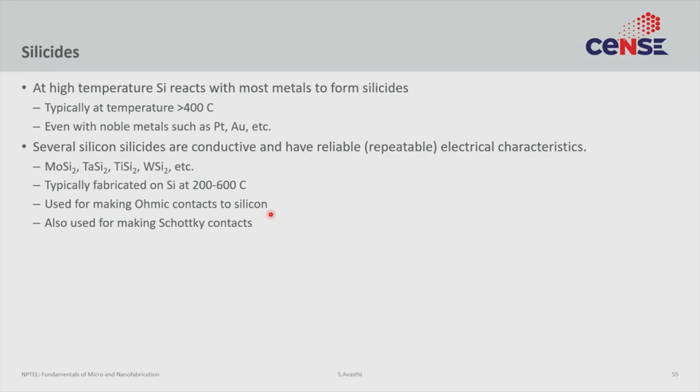So, we have discussed a lot of tricks that we use to clean the silicon surface, and why cleaning the silicon surface is so important, especially before critical depositions. But a lot of those cleaning steps only work for native silicon that does not have metal, because if it has metal, then a lot of those acid cleans we can't do because of chemical incompatibility. But even with hydrogen passivation, even with hydrofluoric acid dips, there is always a little bit of oxygen on a silicon surface.